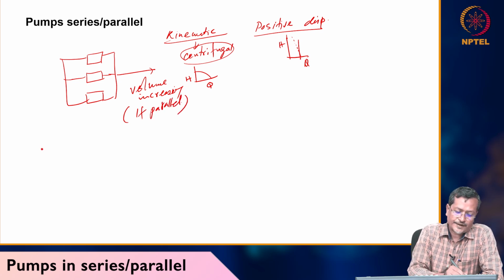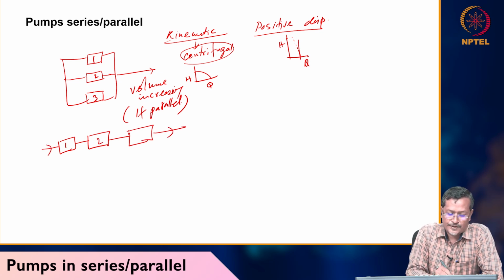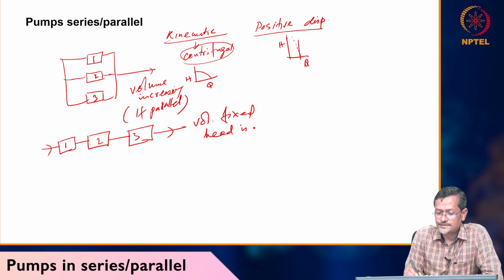But if you are connecting in series, pump 1, 2, 3, like this, in that case total volume is fixed, but head is added or increased.